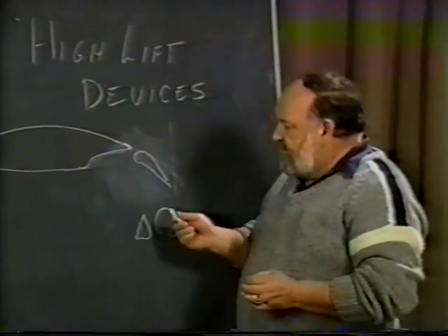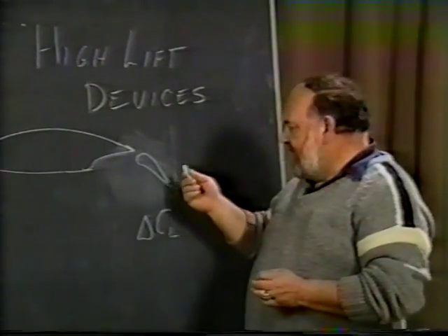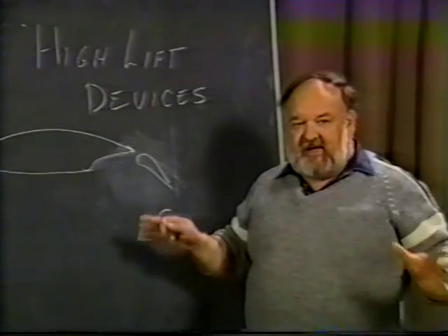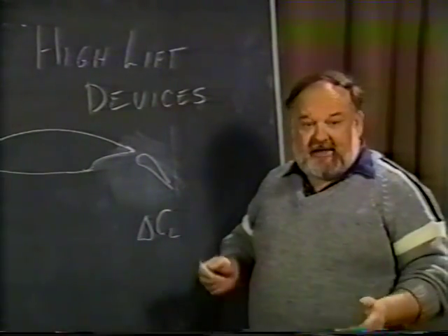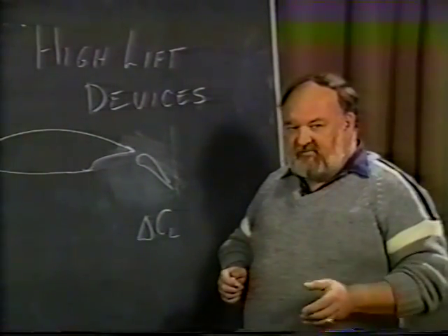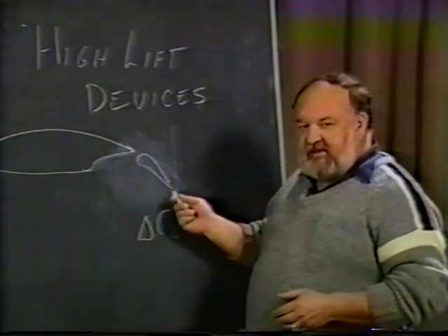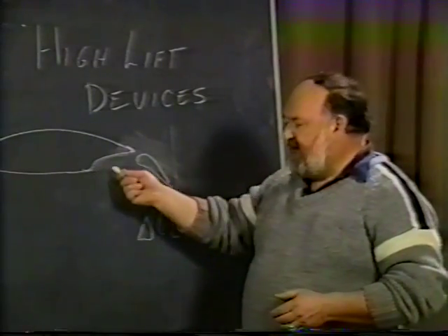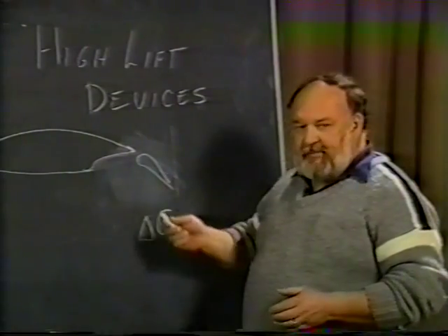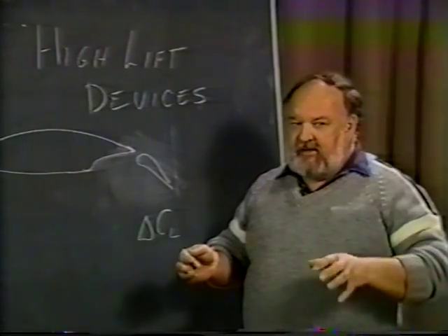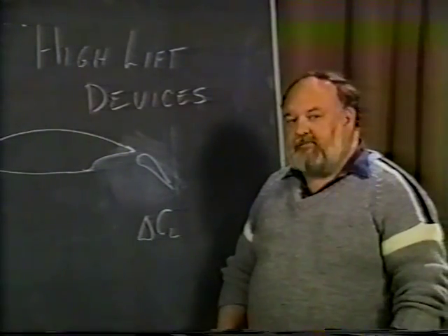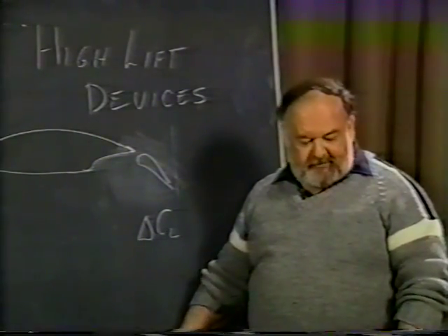So these two flaps, the single slotted flap and the Fowler flap, are essentially the same, but the advantage of the Fowler flap is that you actually have more area exposed. The Lockheed Connie, the P-38, a lot of Lockheed's airplanes use the Fowler flap. The disadvantage is that you probably have to have a track assembly to activate this flap, and that's much more difficult to make. It involves rollers and cams and other assemblies, which can present maintenance problems.